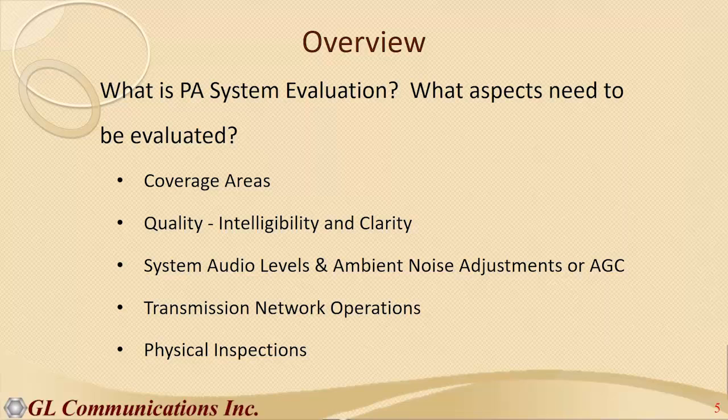And on top of that, and it plays into all that, system audio levels and the ambient noise adjustments. A lot of systems, as you probably know, have ambient noise microphones that will feed an AGC to lower or increase the volume of the PA system. So is that all working correctly? Has it actually been configured correctly to work correctly? Let alone a problem in the field of a degrading component. Has the system been designed correctly or even configured on site correctly? These things are typically what we would run into.